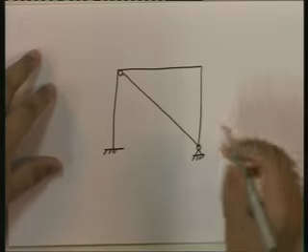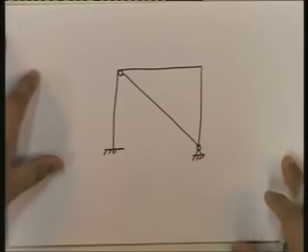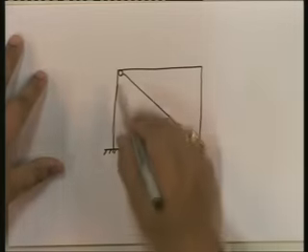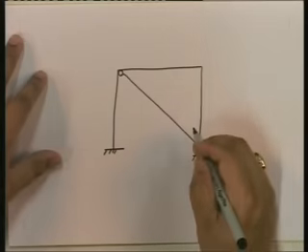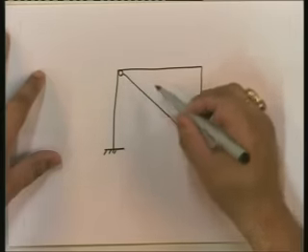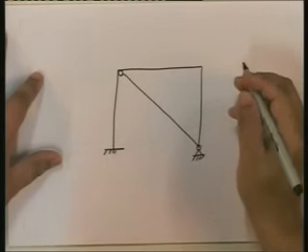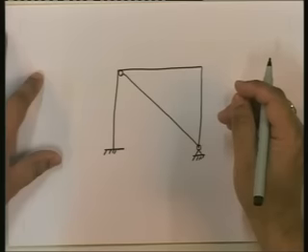Now this is the problem that we are looking at. What you have is a frame, and this is more in terms of a braced frame. This is a bracing. Bracings typically are pinned at two ends, because bracings in a frame are essentially to stiffen the frame and to take axial forces only. Bracing members are not normally designed for flexure.